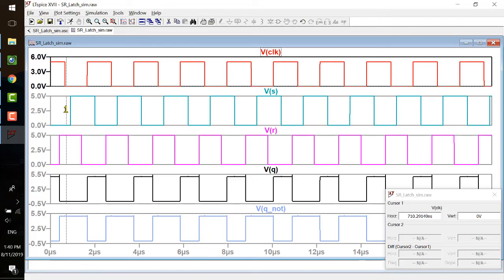Okay, so after Q is being reset and clock becomes 0, this is a super strong 0 here, which will kill all the Nand Gates and force the flip-flop to memorize the previous state. The previous state is 0 here, right? So it's going to be memorized all along the way until here, because the clock is 0, it's trying to memorize that. And then at this time point, clock becomes 1, so your flip-flop comes back to work again.